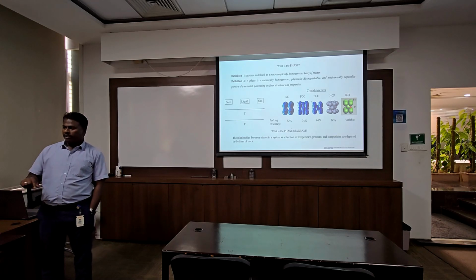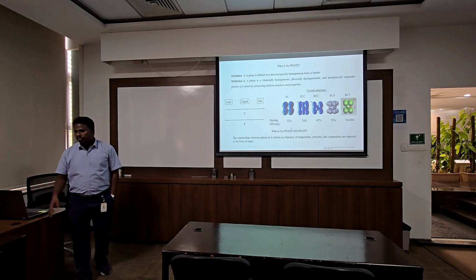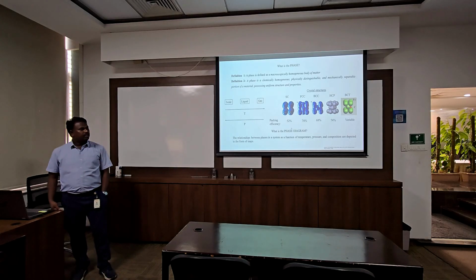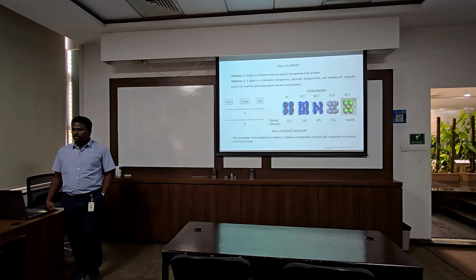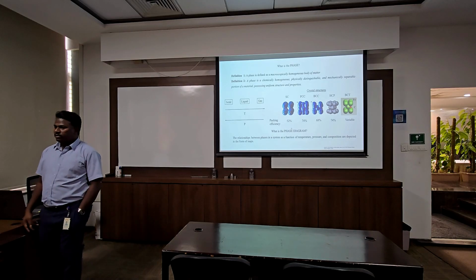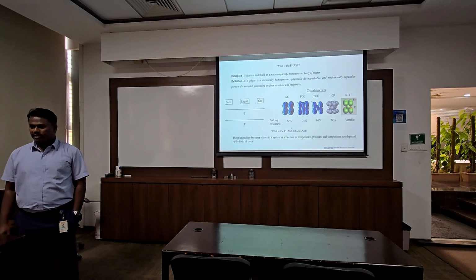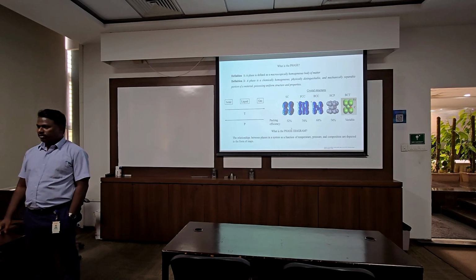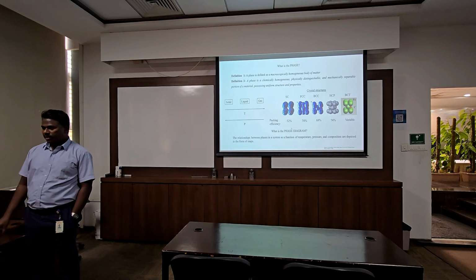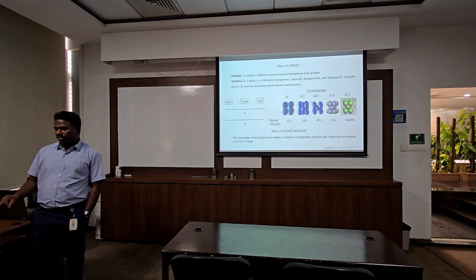stable. When you increase the temperature, low packing efficiency structures will form. If you reduce the temperature, for example, considering FCC and reducing the temperature, that is also more stable. It is the maximum packing efficiency, so the theoretical 74 is the maximum. Even if you apply heavy pressure and temperature, it cannot go higher than that.